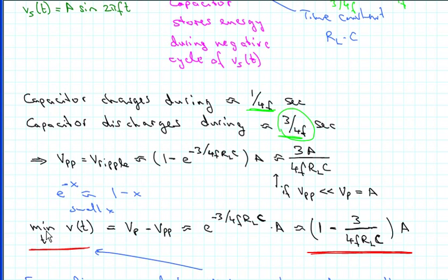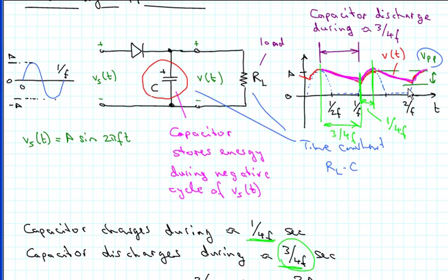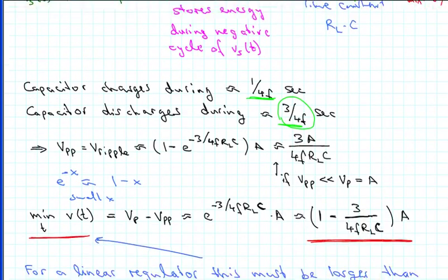And another quantity that's important for the design of power supplies is the minimum voltage that we are getting here. So that would be, if we look at the bottom of the ripple, V minimum of V of t, and that's the lowest voltage that we are going to see, and it has to be higher than the output voltage that we would like to produce with a power supply if this is going to work well.